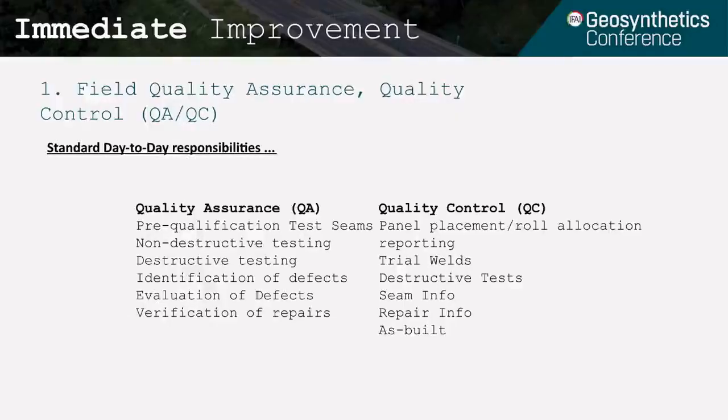Assessing constantly changing site conditions, examining proper heat seal and grinding techniques, monitoring welding equipment and deployment methods, and all of the above which are directly related to the system's long-term sustainability. Their role should lean heavily on making sure physical install performance is of good quality, not just that the documentation